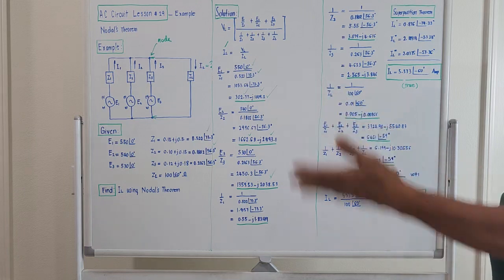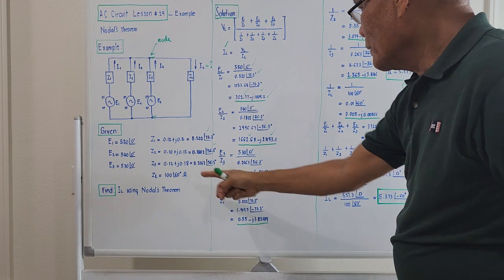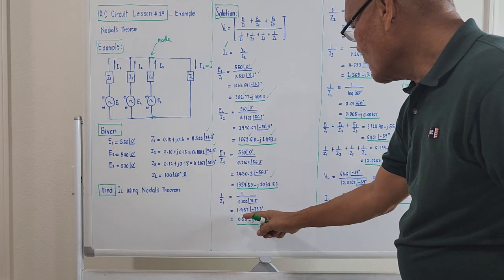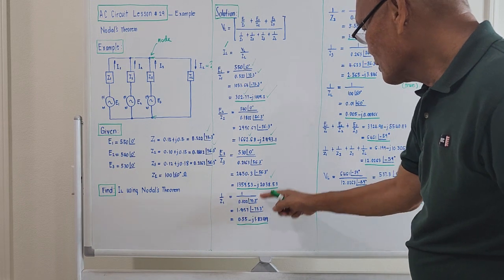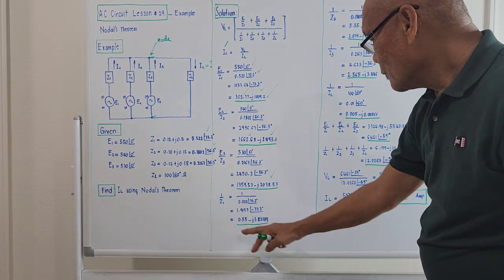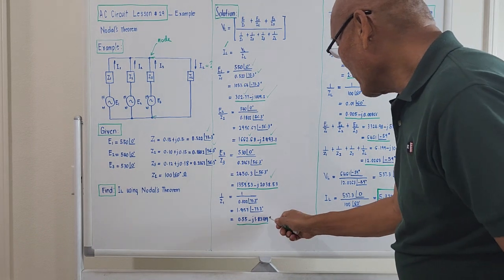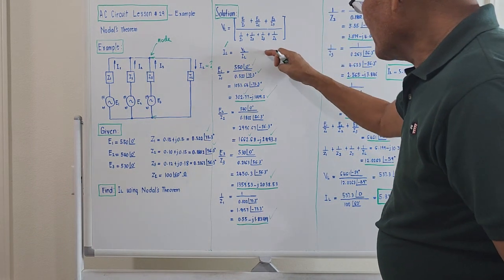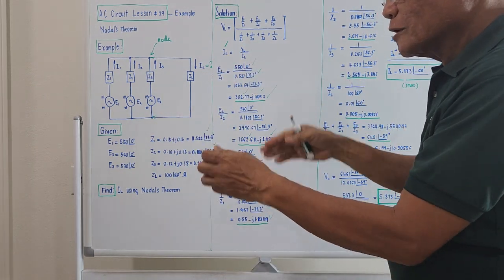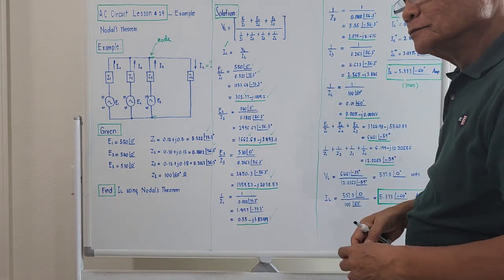Okay, let's go with the bottom portion. 1 over C1. 1 over C1, we are given C1 in terms of polar, right? 1 over this, 1.9157. This goes up, negative 73.3, converting to rectangular, 0.55 minus j1.8349, rectangular. Why did I change to rectangular? Later on, upon reaching the denominator, we will again take the sum. So it's a must that we should convert all the things under the denominator in rectangular form.